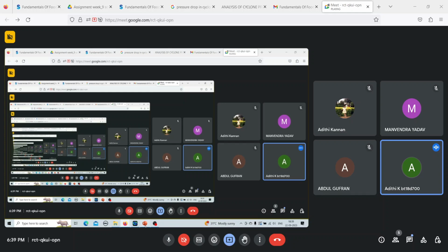If you remember the process of the cyclone separator that we discussed in one of the previous questions, the answer is longer time. In a cyclone separator, you send in the dirty air that contains suspended particles at a tangential velocity, and it will come down the cyclone separator in a spiral manner.